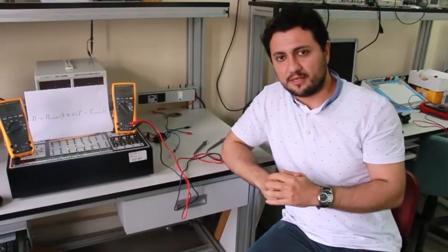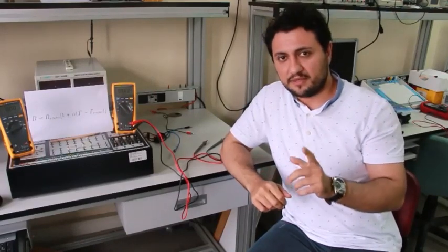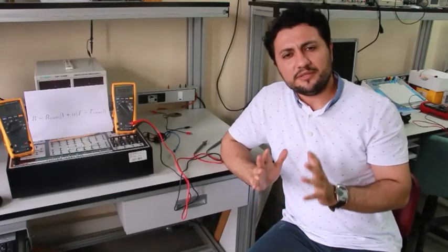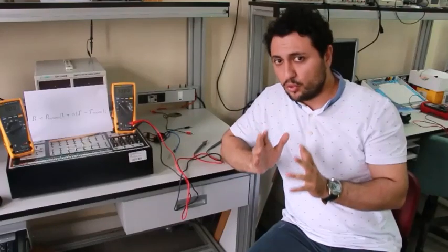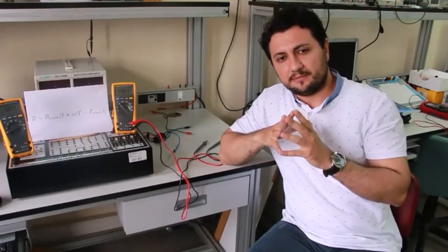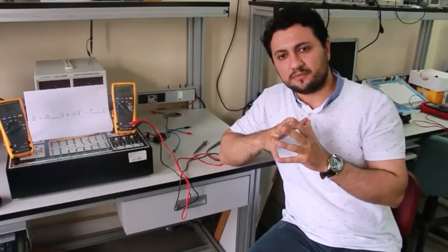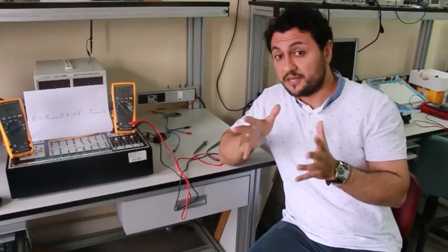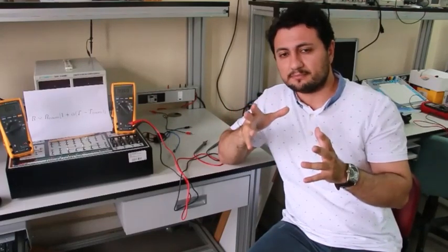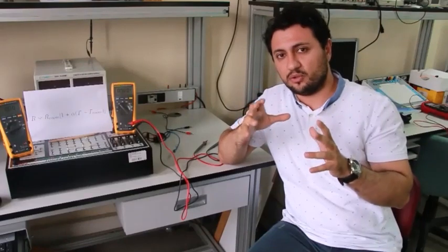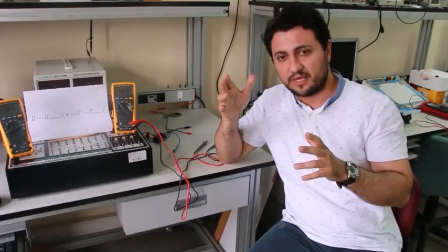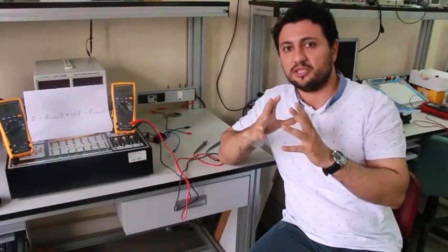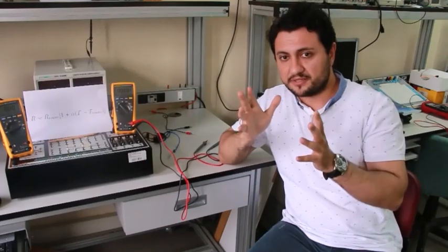But before that, I want to remind you of something about the material. Generally, the resistance of a material depends on the temperature with a thermal coefficient of resistivity. Because the tungsten metal has a large temperature coefficient, the resistance of the bulb increases as the filament heats up. So, if the voltage applied on the bulb increases, the brightness and the temperature of the bulb will increase.